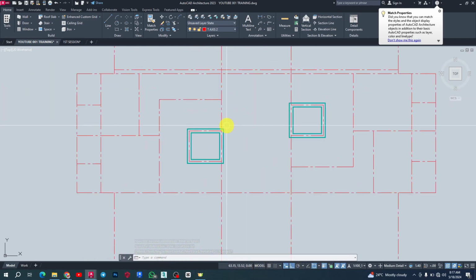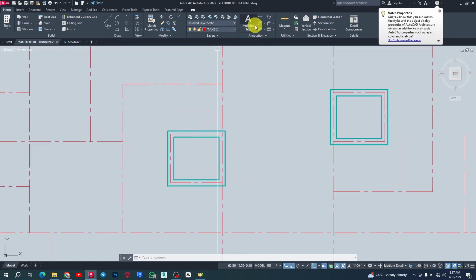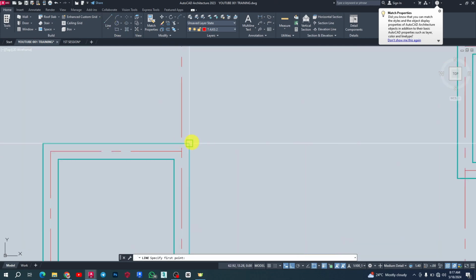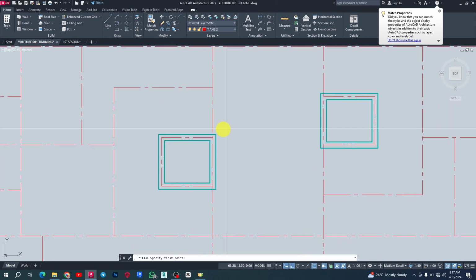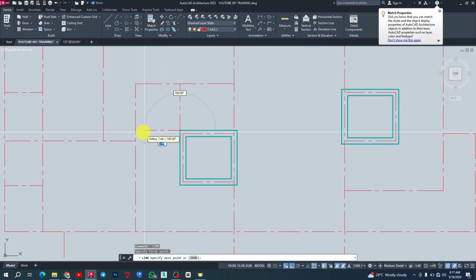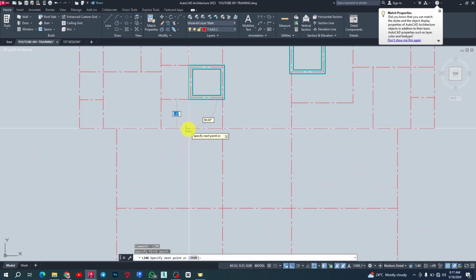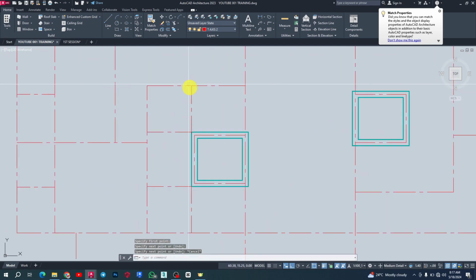Okay, so for the staircases, since the width of my beams is probably approximately 250, I'm going to go here, and then from here I'm going to minus 1.25, but that is not even really important. I can just start from here. This is another landing, since it's a dog-leg staircase, right? This is an open well staircase. So I'm going to start from here and create the landing here automatically, right?